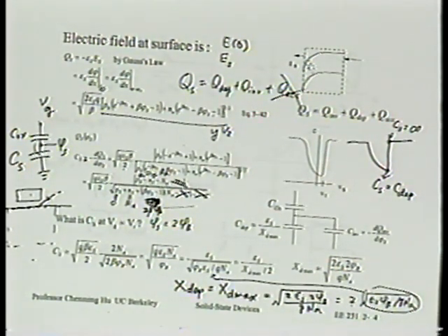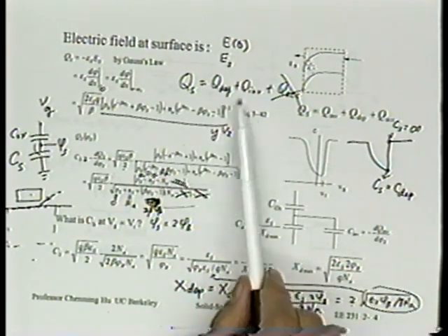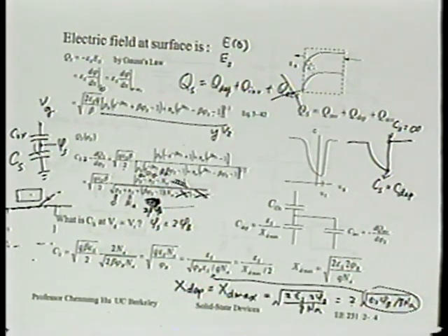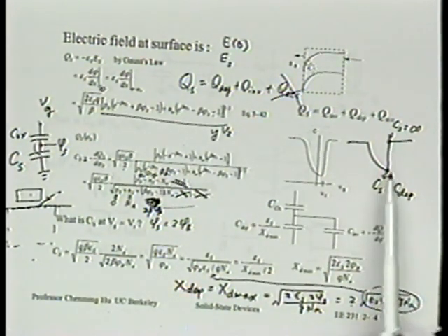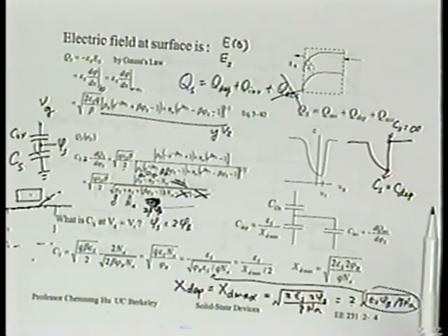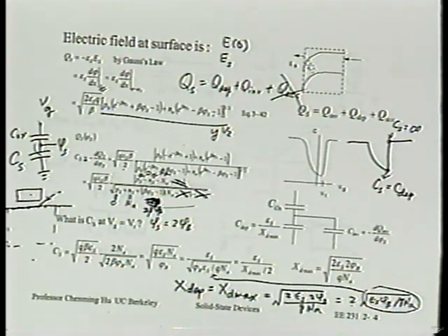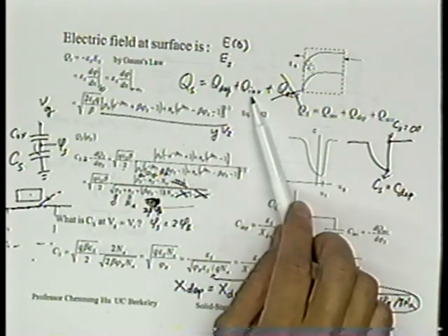What's new is that the second term will also give us a capacitance. You probably have already had this uncomfortable feeling before. That is, how could we assume there's no electron at this threshold point? We already said the concentration is equal to the doping concentration. That doesn't seem to be a small electron density. And indeed, it's not negligible. This term is fairly significant.